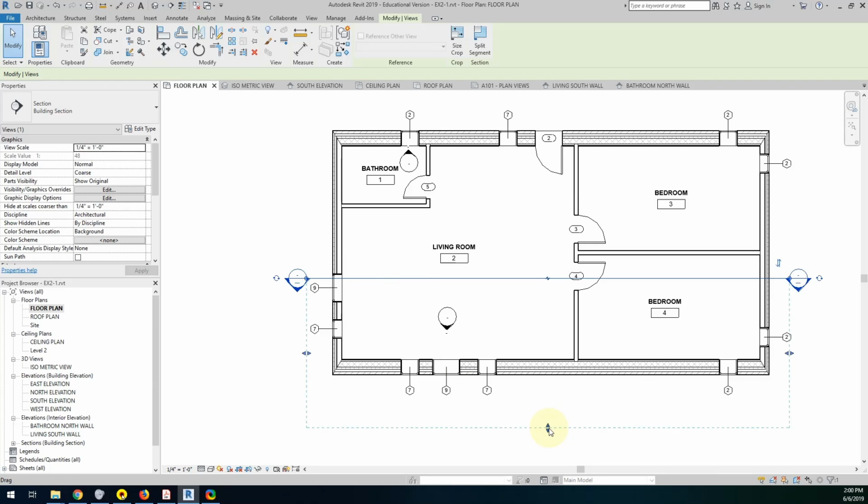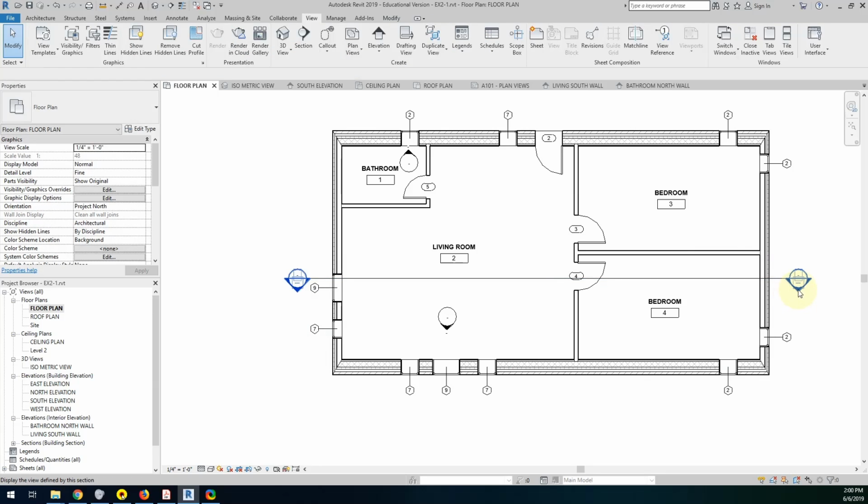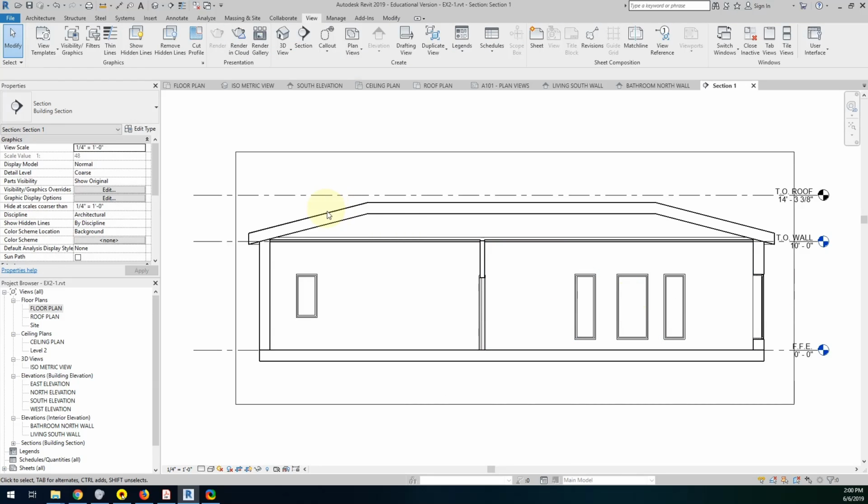Again, like the detail view, there's how far it's rendering into, and then the little grips on the left and right are how far on the crop from left and right it's also rendering. The arrows point in the direction in which it's picking up the detail. If I double click on a head, escape once, you can see which way it's rendering. So there's my three windows.